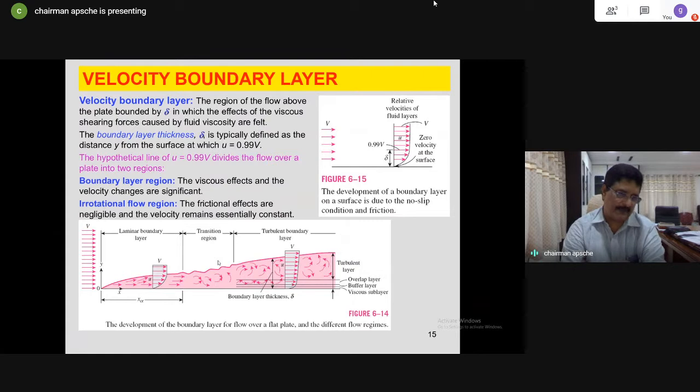Until the flow transition takes place, I said, for all laminar flows, the Reynolds number is lower. What is Reynolds number? Inertial force to viscous force. Initially, the viscous forces dominate the inertial forces, and therefore Reynolds numbers are kept low, and fluid motion is highly laminar. Slowly, as the inertial forces pick up, the viscous forces are dominated comfortably and the flow becomes turbulent.